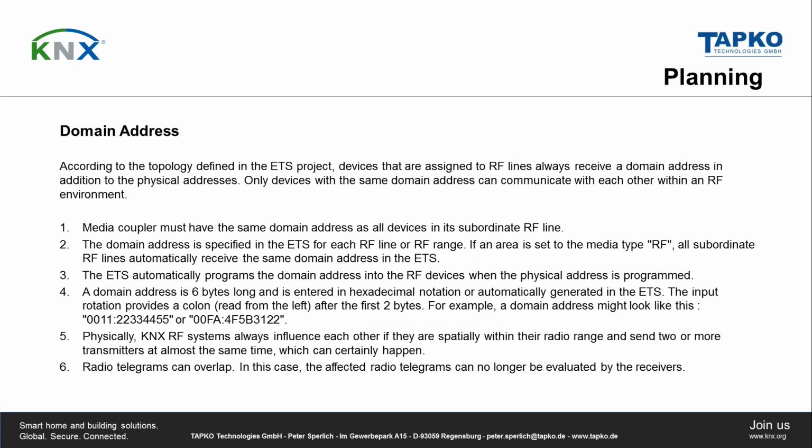This domain address can be automatically generated by the ETS. You see in point 4, maybe 00 FA, and so on. You can also think about your own description for this domain address, so you can give, for example, 0011 or whatever you like.